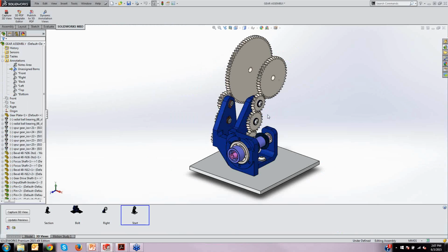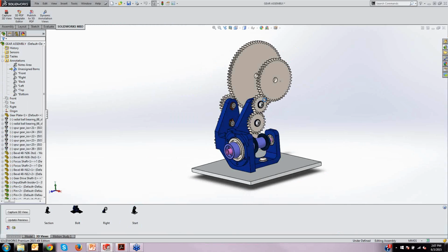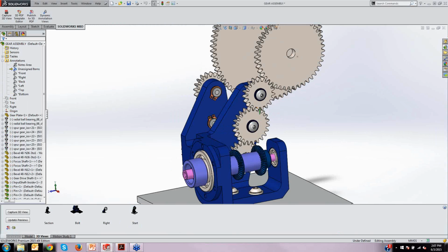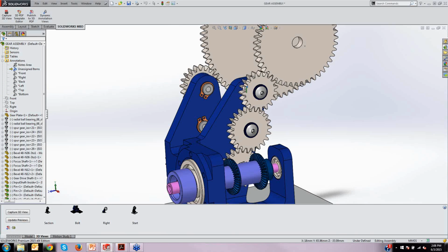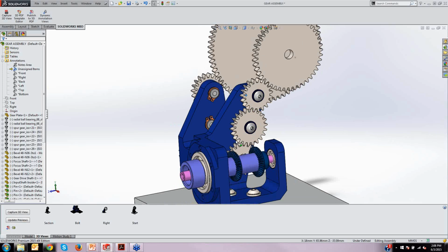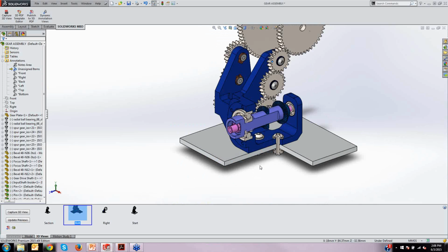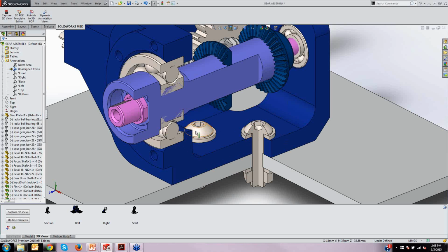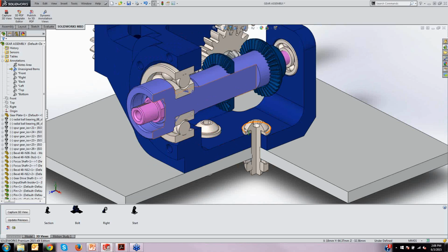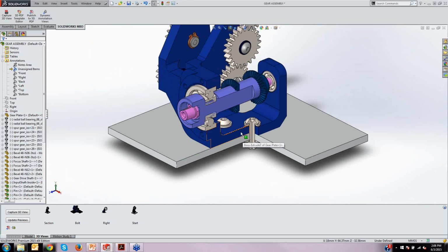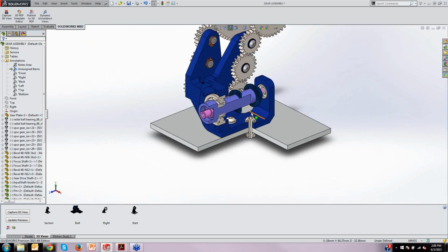This is for an underwater camera housing, and with this housing, we have some tightly meshed gears that require precise placements so that the focus of the camera works correctly. We can see from this section view, just by dissecting what's important on this part, that the location of these bolts is probably very paramount to the actual mounting of this camera housing.